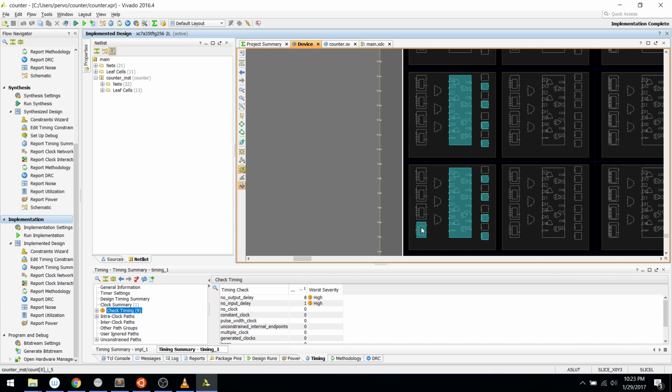Now these are a little bit slower because there's propagation delay. There's a carry chain that goes all the way from the lowest bit to the highest bit. If the value of the register is like 11111 and you do an increment, then there's a carry ripple all the way from the lowest bit to the highest bit. But it doesn't really care, because if it meets the timing constraint, great, then that gives us space to optimize for area like it did here.